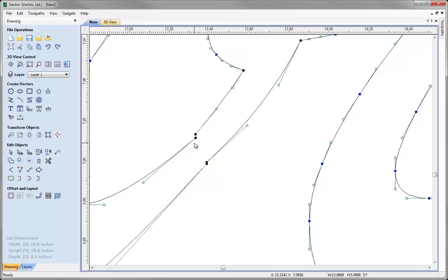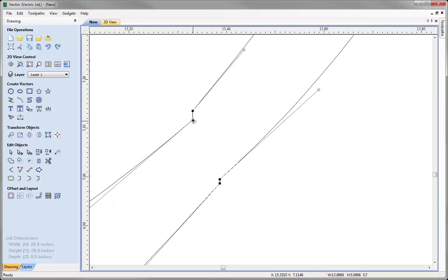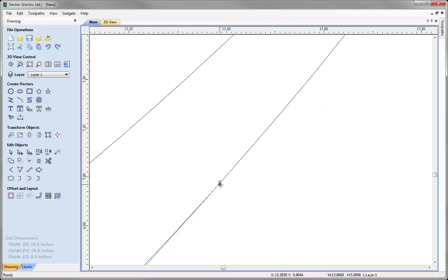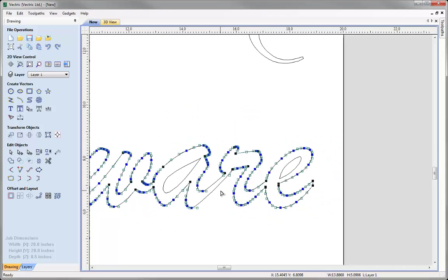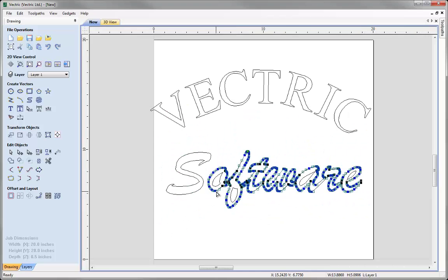text. So if I go here, I can simply hover over the nodes and just delete those, so that when we do zoom out, to the eye, it looks perfect. So if I just press escape and F on the keyboard to zoom to fit. So it's just important to understand that if we do require our vectors not to be overlapping, there are tools available and methods that we can use to overcome that to then get, say, the text that we want to